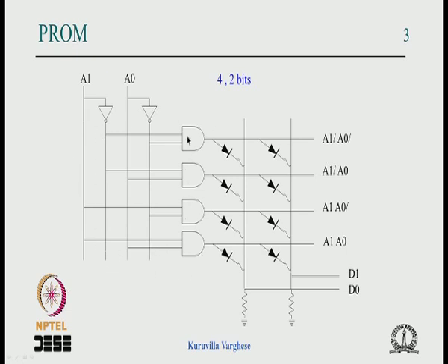Most applications don't require this number of AND gates. For chip select decoding it's very few, 1 or 2 AND gates, and even in a normal Boolean function the number of AND gates required is small. So people reduced the number of AND gates but made them programmable, and the requirement of minterms vanished and we came to the product term.